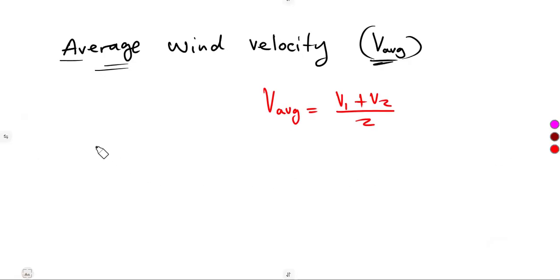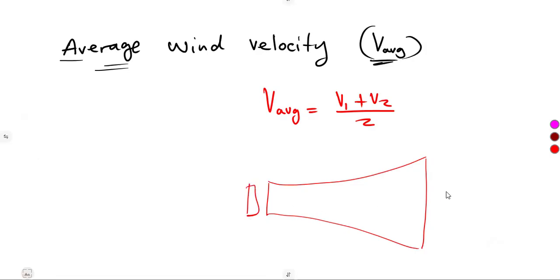That is what we are going to have as the average velocity, taken from the conditions of the streamline, where we are given the wind streamline through the turbine. Just like when we are dealing with nozzles, you will have where it is entering, then we also have the exit.